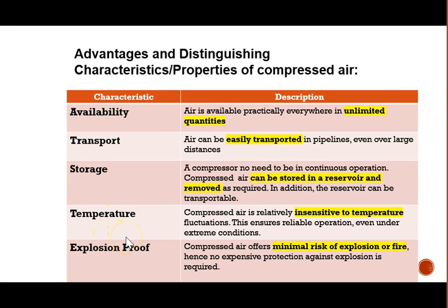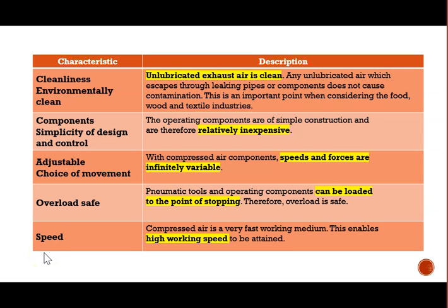And then temperature, okay, they are not really sensitive to temperature and can be used even in extreme conditions. And then explosion proof, in which there is minimal risk of explosion or fire because they deal with air. Okay, and in terms of cleanliness, the air is very clean, and when we exhaust the air from the system, it can be released straight to the environment.